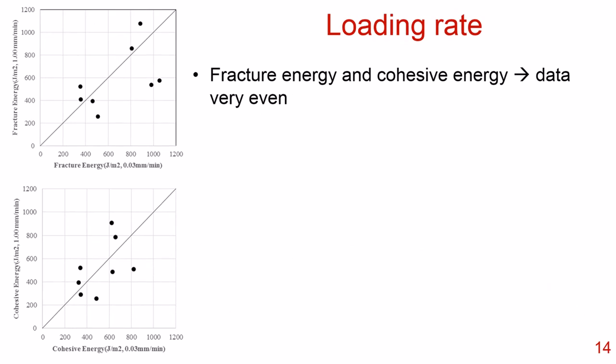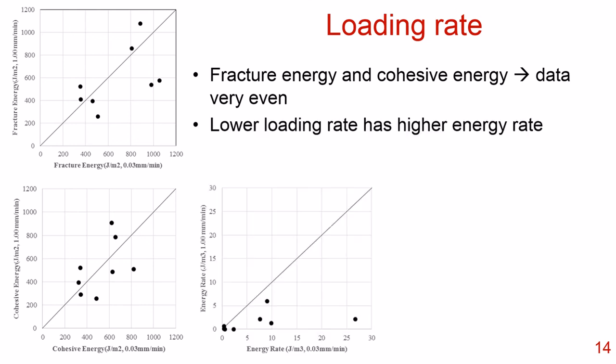Now, finally, the loading rate. We did not see any real trends with the fracture energy or the cohesive energy with loading rate, but here the lower loading rate had a higher energy rate. So the loading rate is not as clear as temperature. It is a little more similar to asphalt binder and the aggregates.